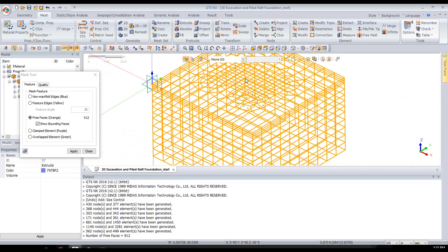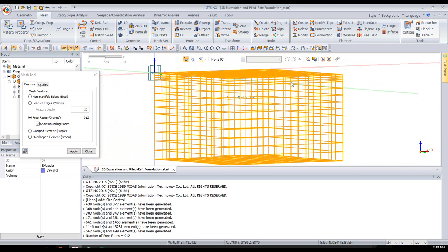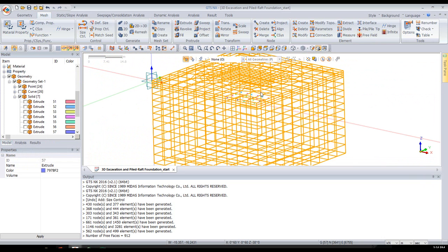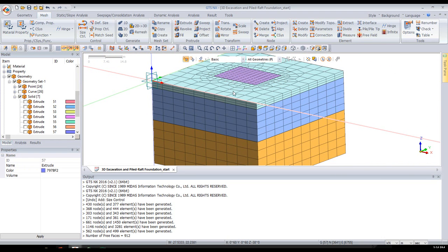If the inner layers meshed were not connected to the outer layers, then I would actually also see the rectangles or the cubes inside, telling me that these are not free faces, that the program has not connected them properly. But because here I only see the outer boundary, it tells me that the program recognizes that everything is a single mesh and it's all connected. So I can now proceed to the next step, which would be to extract or generate my walls.